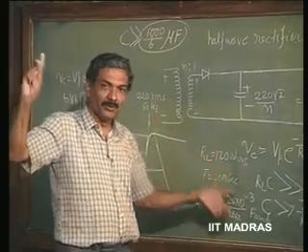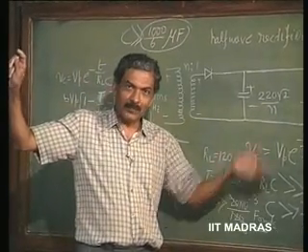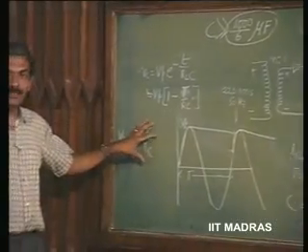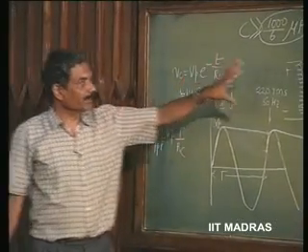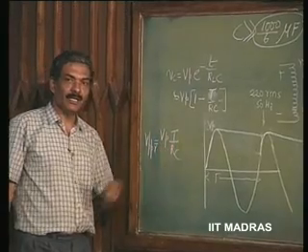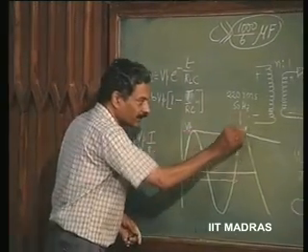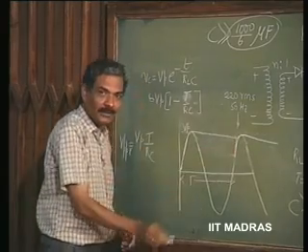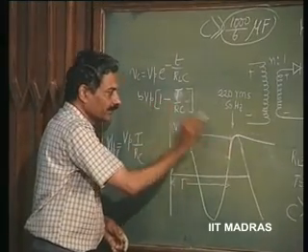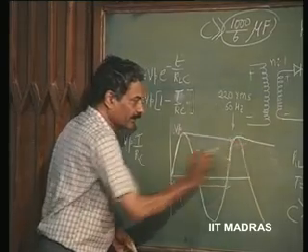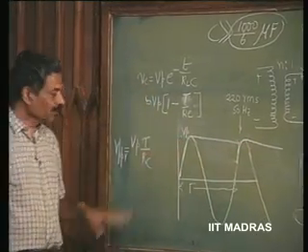So, by putting a huge capacitor here for the load RL, I have been able to retain the DC almost at V p itself, and there is a ripple of V p into T by R c. I can approximate this waveform as a sort of triangular waveform, because the discharge is occurring linearly and again increasing, again decreasing. This ripple voltage is what is occurring there.